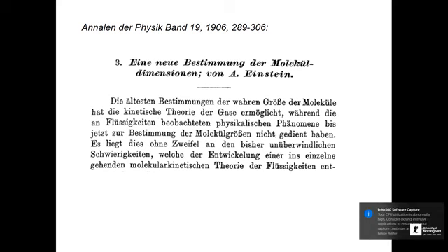And it was basically a shape factor, and for a sphere, this viscosity shape factor he worked out to be 1. And for some years people used this calculation, and then they found problems with it. You could work out things like Avogadro's number from this viscosity shape factor for spheres of 1, and people were coming out with quite large discrepancies, large errors.